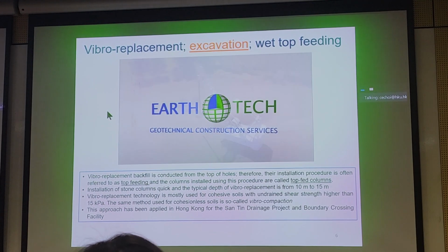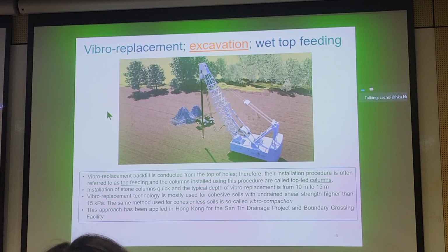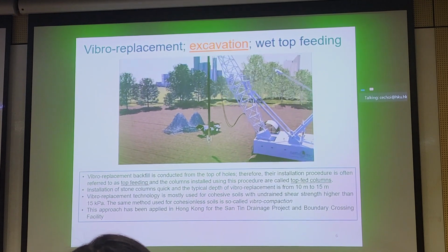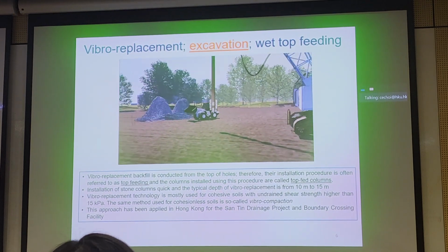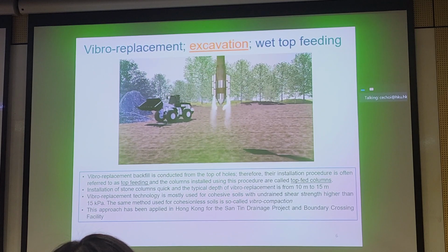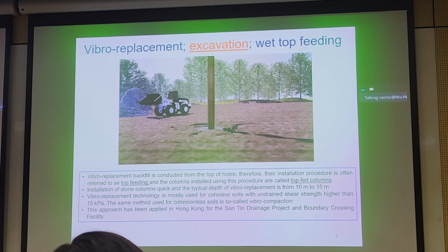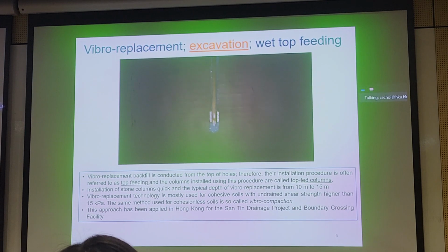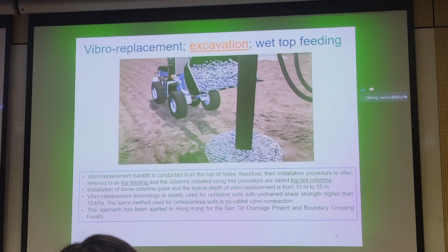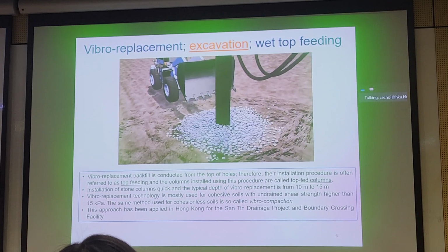These videos were just extracted by hunting them down on YouTube. There are lots of interesting animations created by various construction companies with specialized equipment. And of course, these are specialized equipment; you would have to hire a contractor. So that's a vibrating probe, and it's wet feeding because there's actually flushing fluid used. You have a jet being constantly flushed into the ground to push out soil, and that's the excavation process.